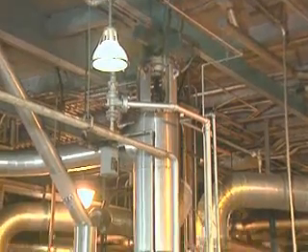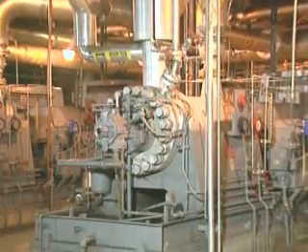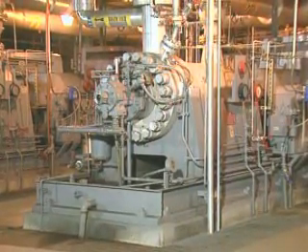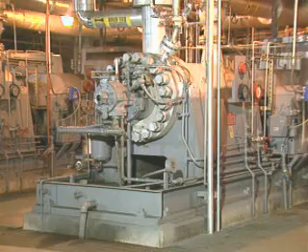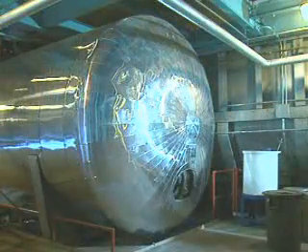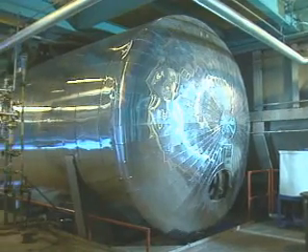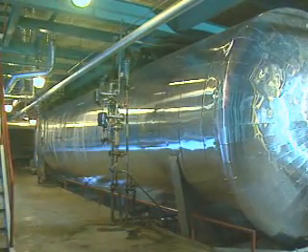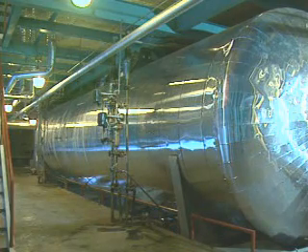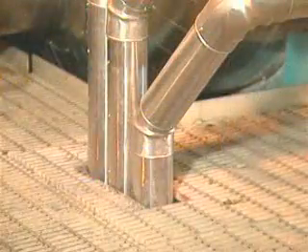For example, if boiler demand increases, the boiler feed pumps begin pumping feed water from the storage tank at a rate that's greater than the rate at which condensate is being fed to the tank by the condensate system. The hot surge tank supplies enough feed water to meet the increased demand for the short time it takes for the condensate flow and the feed water flow to become equal again.